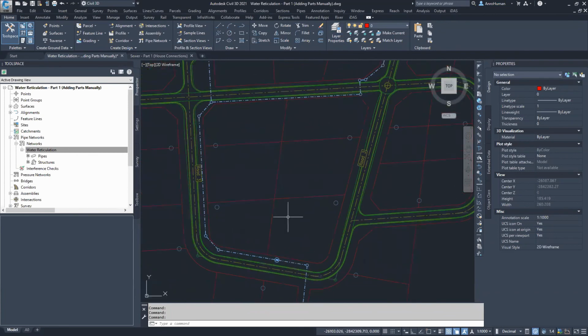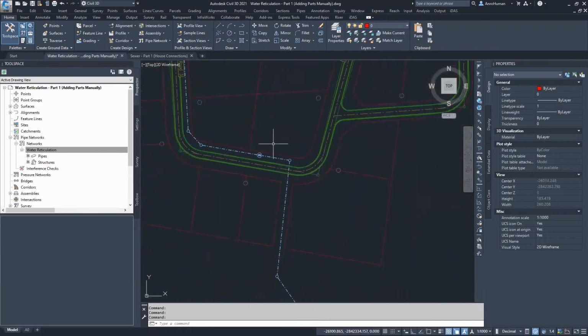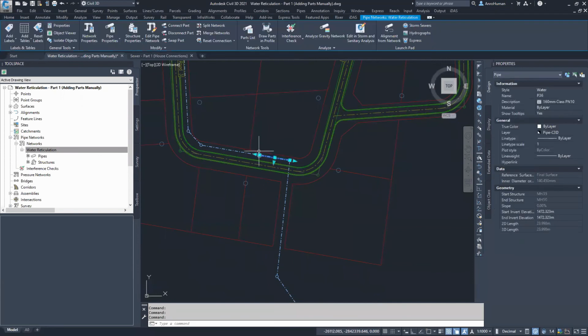All right. Next up is actually how we can manipulate the naming of these pipes. So anyone that has worked with Civil 3D might have encountered this confusion in the past. For example, when you split a pipe, you'll see this one is pipe 36. I did have pipe networks earlier in my model, so it actually names them sequentially from there on. Okay.